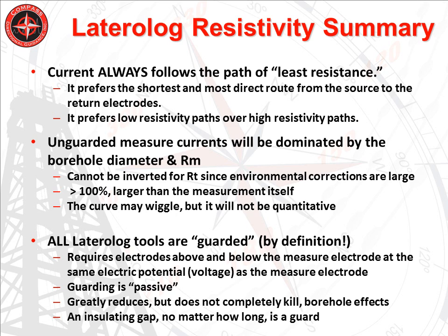Now we can finally answer the question, where do the currents flow? Electric current prefers to follow the path of least total resistance. This path is a combination of the shortest and most direct physical route together with the lower values of material resistivity. The current doesn't flow exclusively in any path to the exclusion of the others. It divides itself among several different paths. The path with the least total resistance will support more current than a nearby path with more total resistance.